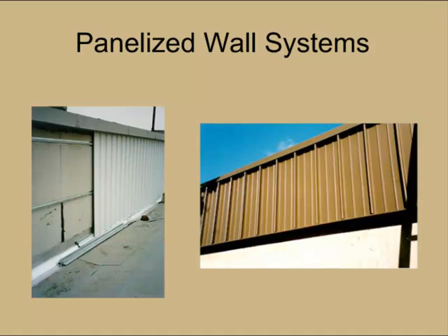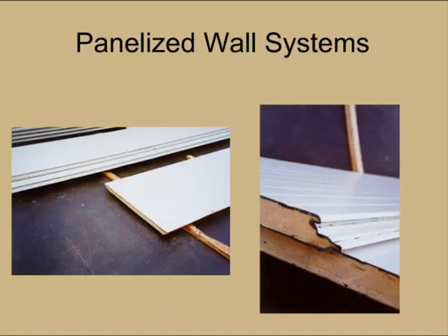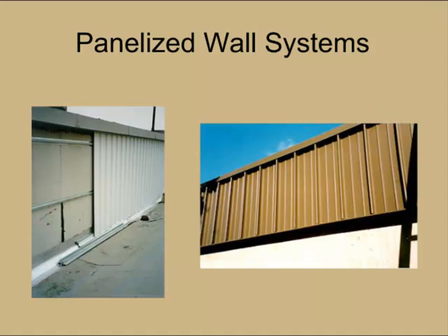The photo you're seeing here is some examples of insulated metal panel wall systems. You see there's a tongue and groove type system there that provides a weather lock between the panels to minimize moisture intrusion. A simpler type system here is just the single ply metal panel over a light gauge metal girt system.